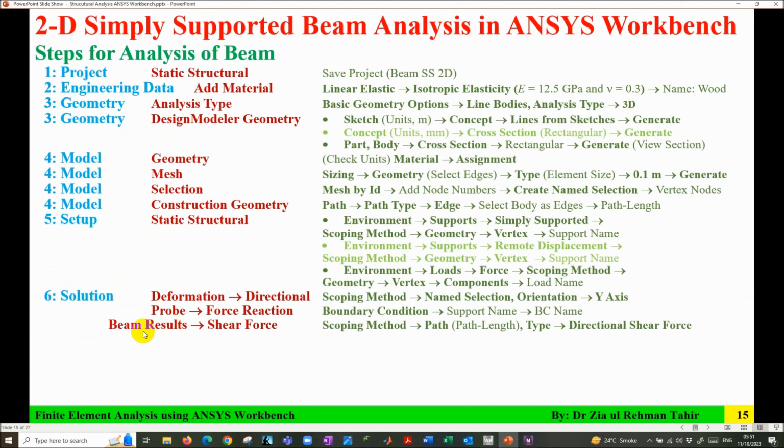Next step, in the solution, beam results, shear force: the scoping method is a path which is already created, and then the type is directional shear force.